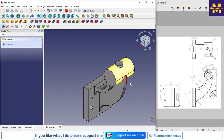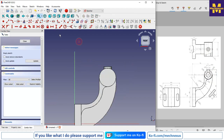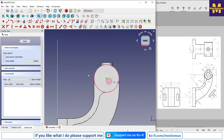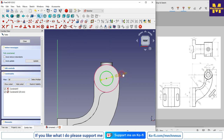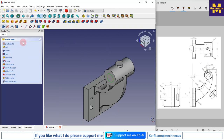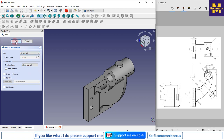Now we will select this face and create a sketch, and we will project the circumference of the circle, create a circle, and cut diameter is 20. I will say extrude cut, will say through all, say OK.